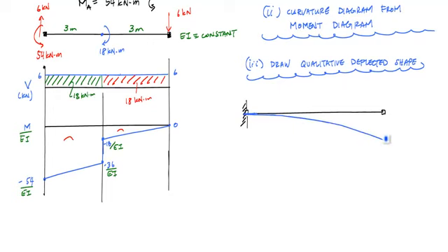When you analyze a cantilever beam using the moment area method, you really want to be able to know some slope or deflection at some point, and boundary conditions are really good places for this, especially in the cantilever beam, because here at the fixed support, you know the slope is 0 and the deflection at that point is 0. So this point A in our problem is a good reference for us to find the slopes and deflections at any other point along the length of the cantilever.